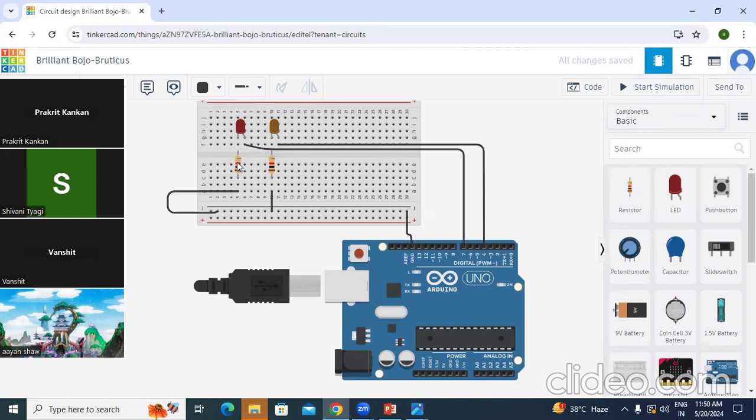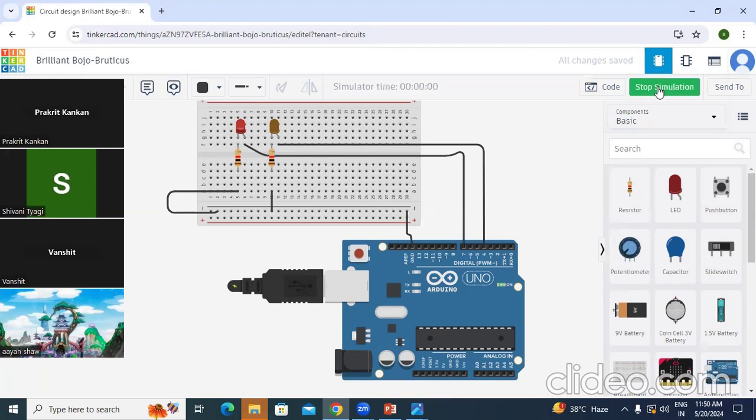Okay, it is showing an error. You can see here the resistor is not connecting properly. In the connection, we have one error. That is, the resistor is not connected to the node. It is in free space. Correct? It was here. So we need to just put it here. Okay, so that is the error in the connection. Now I'm going to start the simulation once again. And now you can see the result is working.